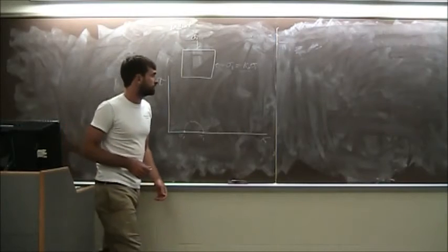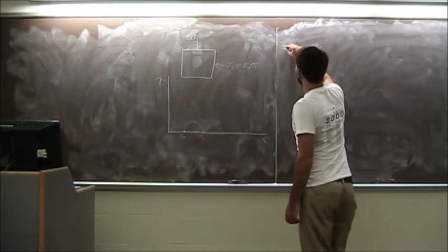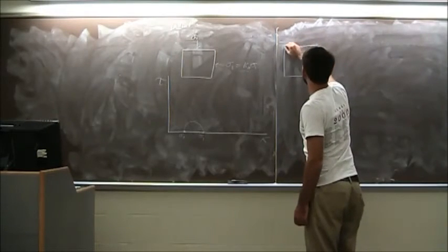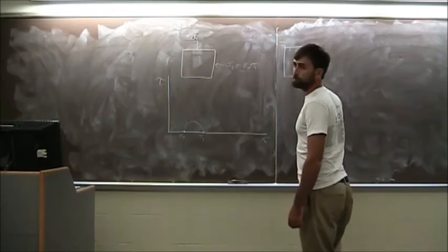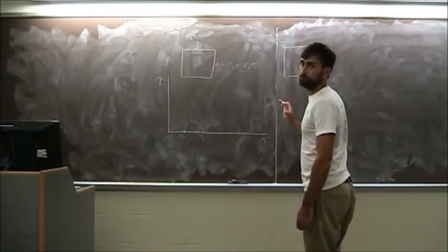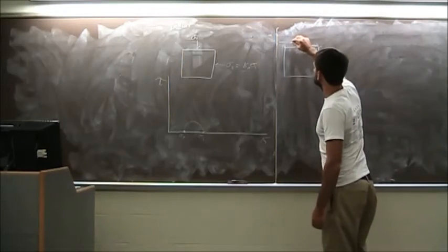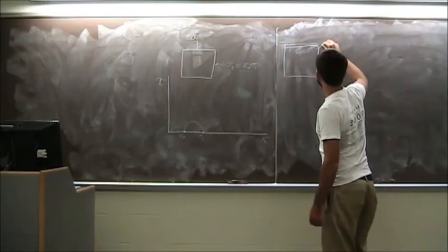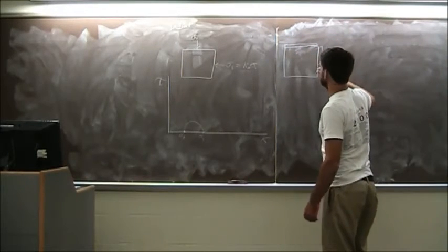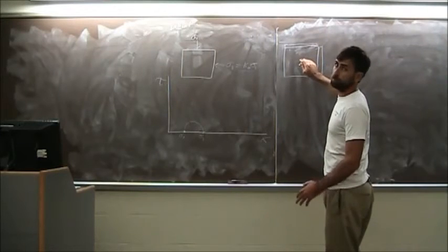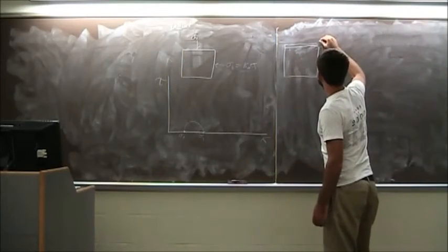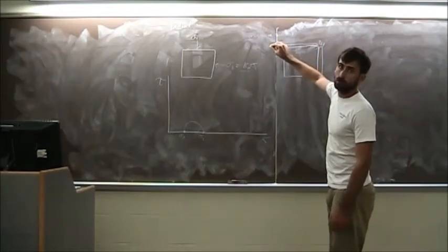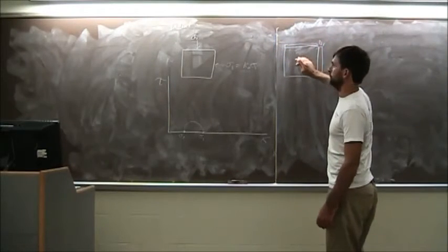But as you shear the specimen, we're going to come into the final state over here. Remember, we induced a failure plane that was horizontal. So now we're going to have shear stress on the horizontal plane, and since this is the element of failure, that's going to be tau failure on the failure plane, because the failure plane is that horizontal plane and it's at the failure condition.